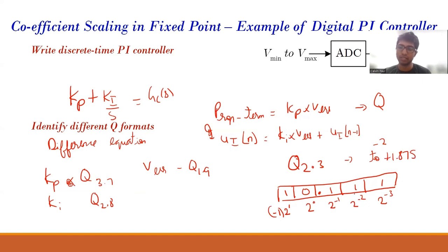Normally the numbers are just integers: 0, 1, 2, 3, 4. But what if I want to get it in this decimal format? For that, we have to use this concept of Q format. And since they are in 2's complement format, the MSB will be the sign bit, and hence we can get negative numbers as well as positive numbers.